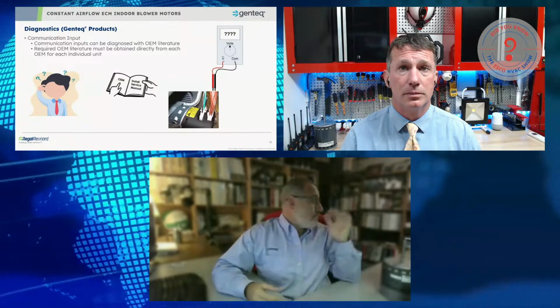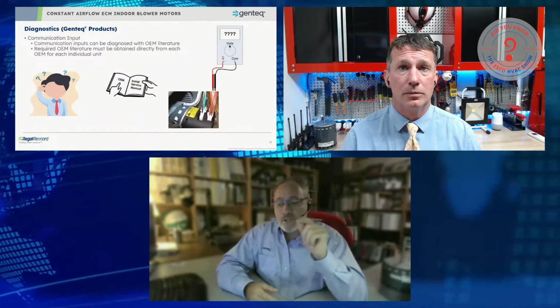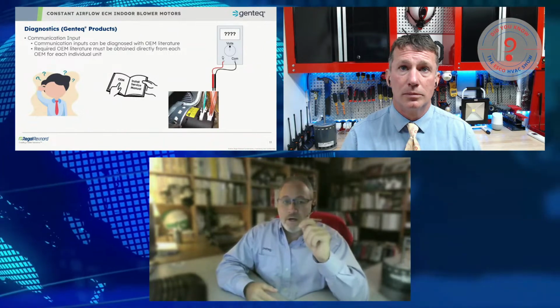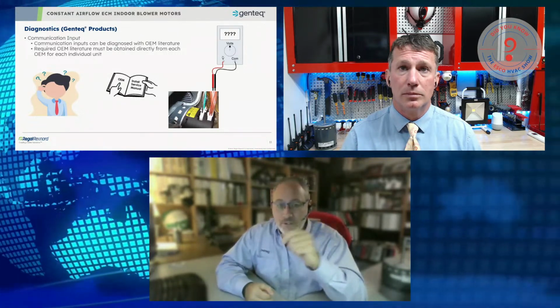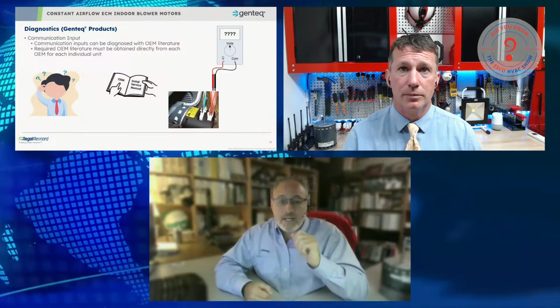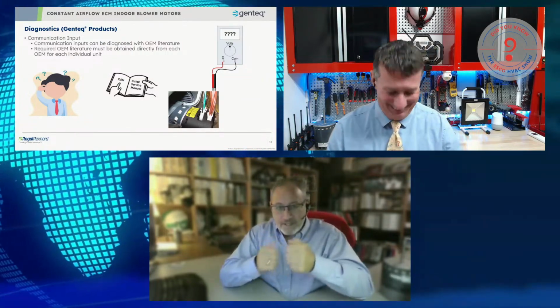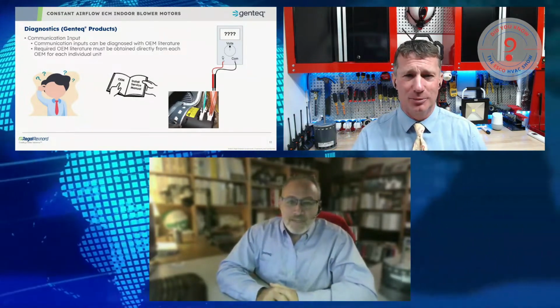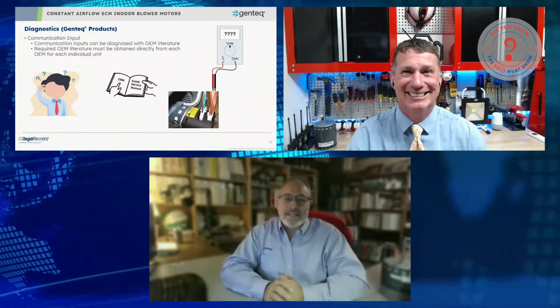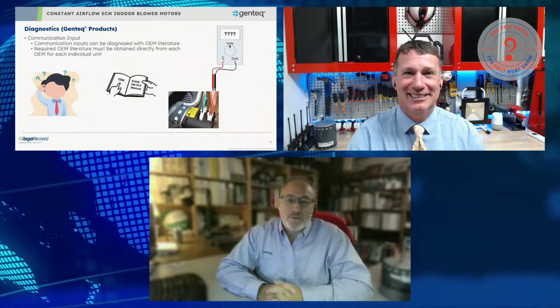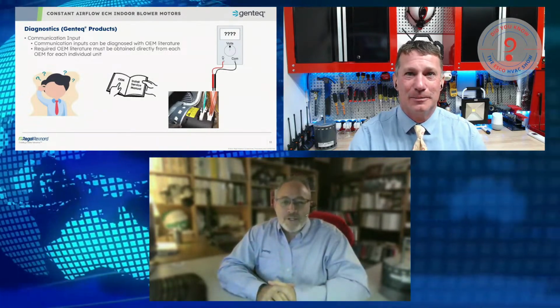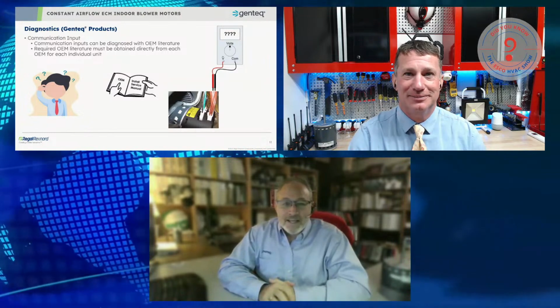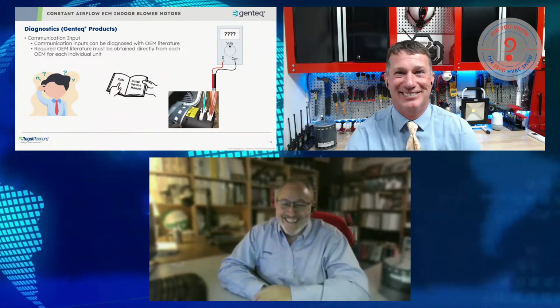Now, I do also want to say that each OEM has done different tricks through the years for testing our motors in their systems. Lennox had a trick where you could take a 9-volt battery, solder some wires on it and connect them to certain terminals. We're going back a little bit now. We are, and I always laughed at that test because Lennox obviously assumed, I'm not picking on Lennox, that a technician had a good 9-volt battery on the truck. So true. Because if the truck was like mine, the only 9-volt battery was the one in my meter that'd been there for a year, or the bad one sitting on the shelf that should have gotten recycled 6 months ago.